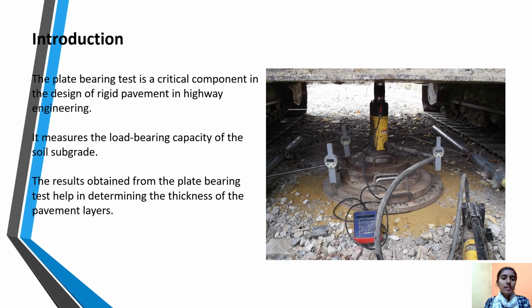The plate bearing test is a critical component in the design of rigid pavement in highway engineering. It measures the load bearing capacity of the soil subgrade. The results obtained from the plate bearing test help in determining the thickness of the pavement layers.